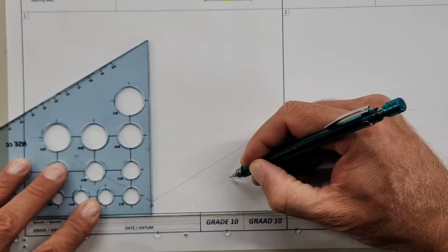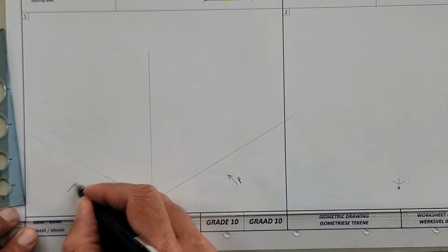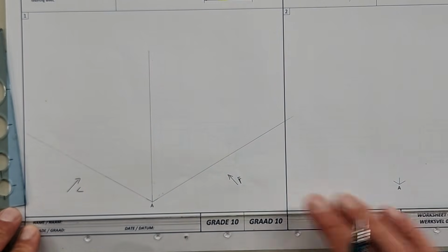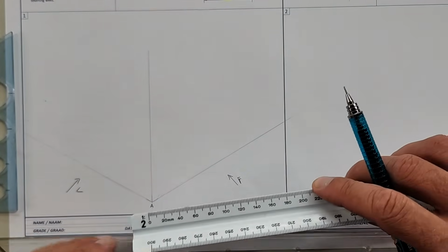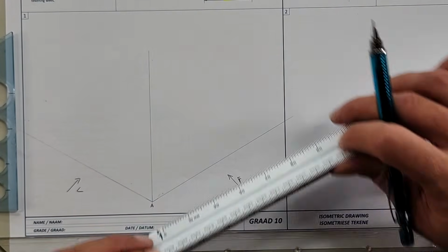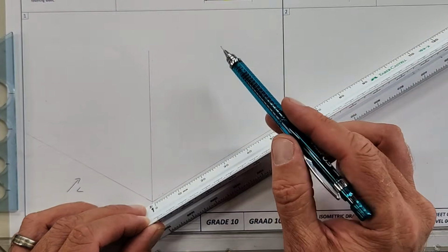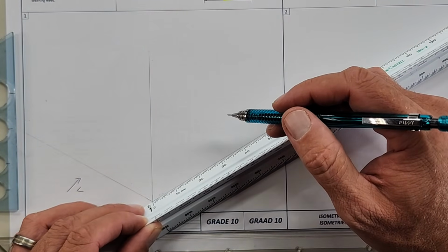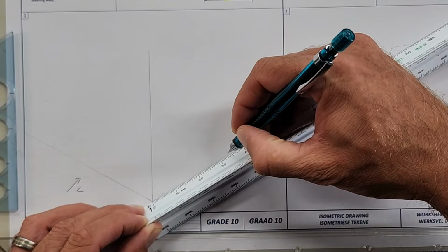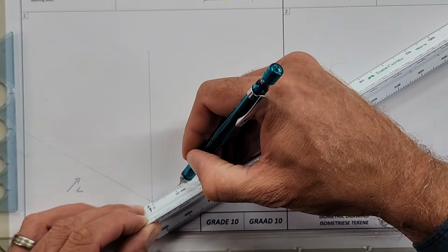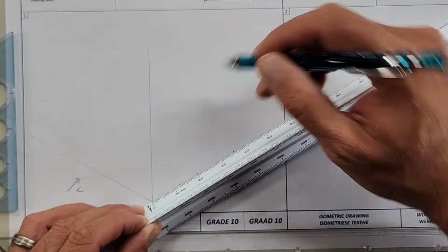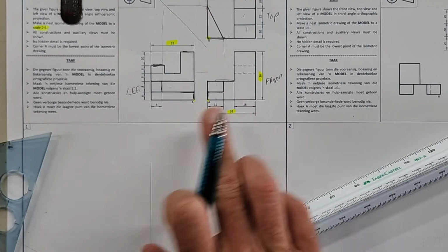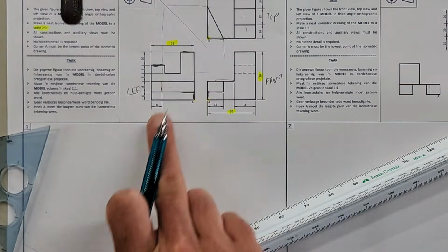Okay, I remind myself that this here is the front view, this here is the left view. The front view's width is 36. Now I have to remind myself it's scale 2:1, so you can find that on your scale ruler. If you don't have a scale ruler, that means you have to take that 36 and multiply it by 2. So here we have 36. We also have a 12. We also have a 16. I'm just using the measurements that are given here. Then the left view, it's 32 and there's an 8 there.